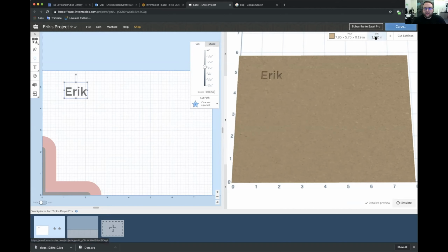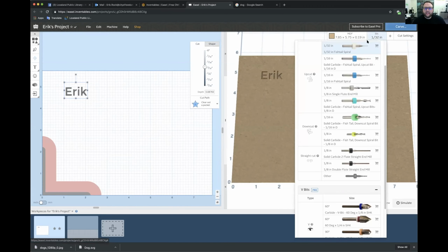This is a good time for me to mention that most of the material has a really hard time with the 1/32 inch bit. Now this is a problem that they did recognize with the machine. It's probably why they stopped selling certain components for the machine. But the 1/32 inch bit breaks on almost every material except for soft MDF. So it breaks on the hardwood, it breaks on the plastics. We've gone through several dozen of these since we've had the machine. So it's a design flaw. It's not awesome, but don't get discouraged. I have an alternative I'm going to mention in a minute.